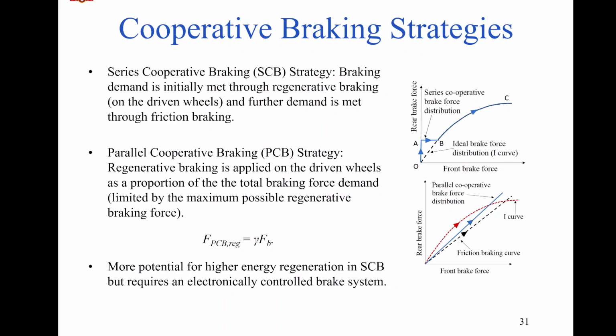I'll reduce my stator current so that the total brake torque I generate, or the total power I recover from the process, is lower. And that by and large gives me even an analog level control rather than three discrete modes of low, medium, and high. Like, how much power am I willing to take from the motor? So we can cap it at that one particular instance itself.